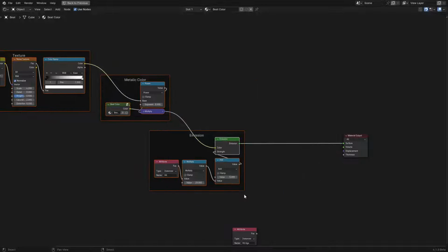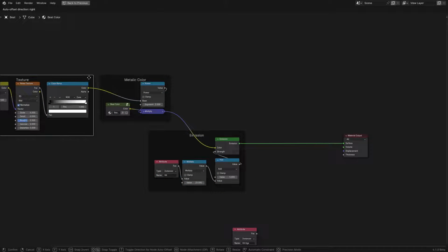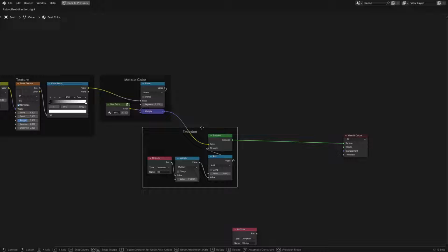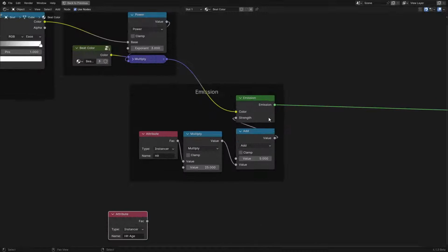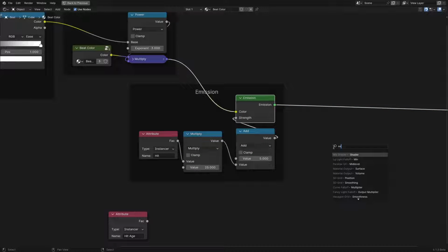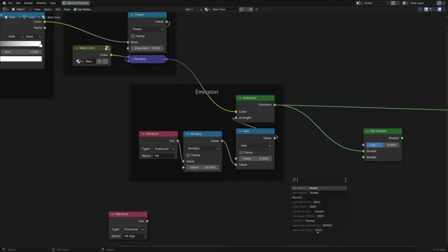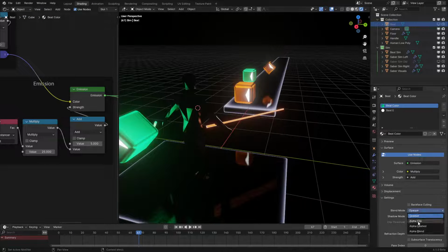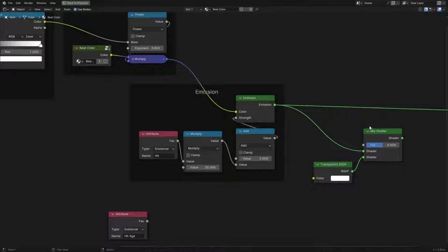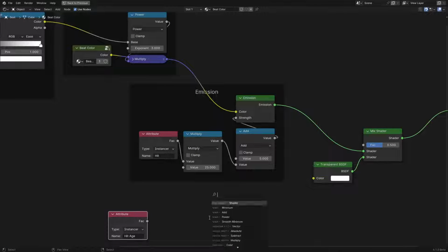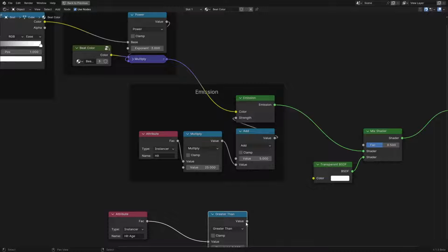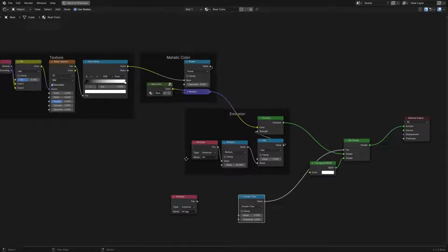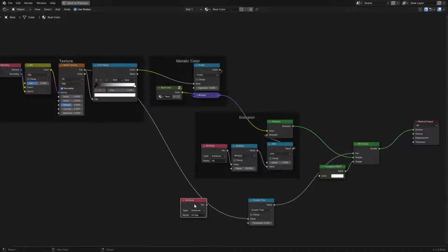So that will have to be a more complex effect, which I'm not the happiest about, but anyway, we'll just do a mix shader between that and a transparent. I'm going to keep this as clipped or dithered, whichever you want to call it, so that, let's see, map range.